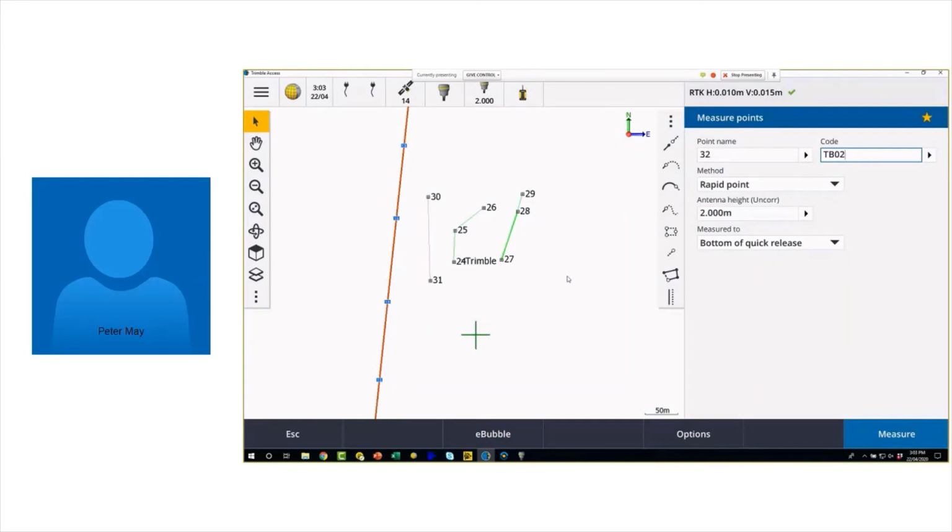I think it depends on the complexity of the survey. If you were running cross sections on a road, and let's say you had traffic management and a limited amount of time to push across and do all of the curb strings, several lanes, and then the other side curbs, I would use string numbering still.